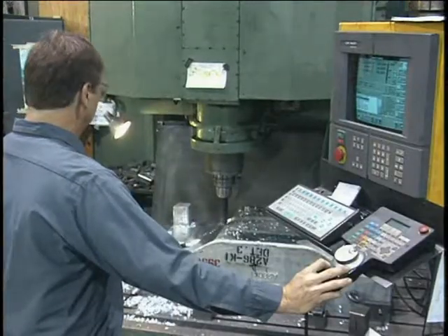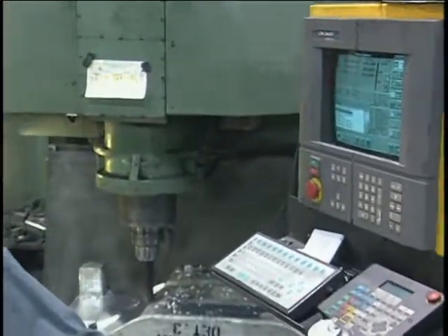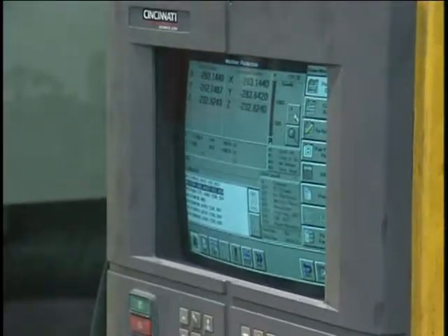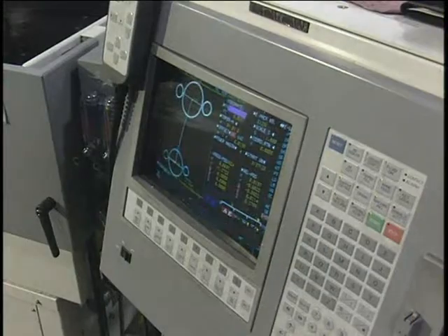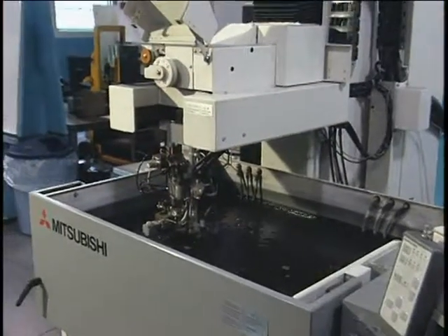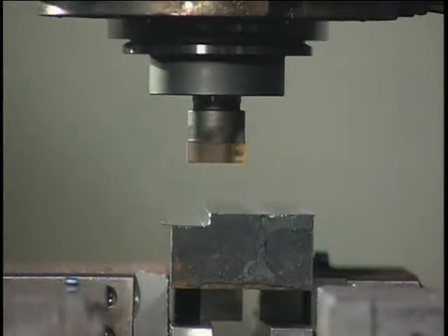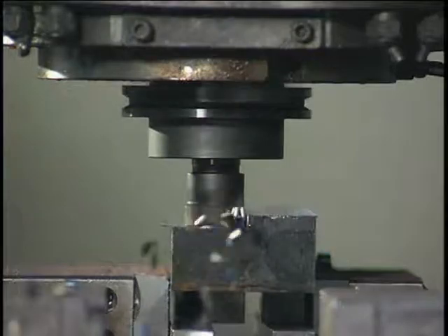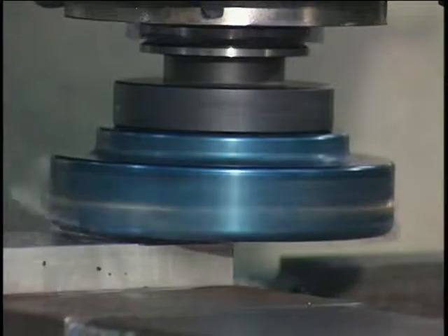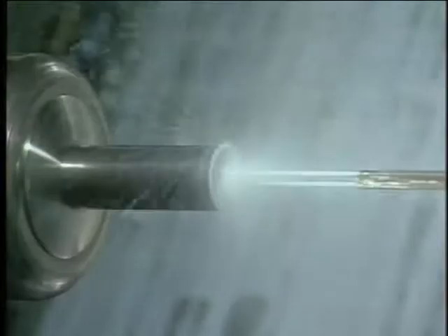Computer numerical control, or CNC, built upon the standard numerical control production capabilities by incorporating an integral computer processor to govern the machine controls. Programmed instructions or data in the form of a part program is translated by the machine control into output signals that control machine functions, such as spindle rotation, cutting tool movement, workpiece movement, tool changing, and cutting fluid control.